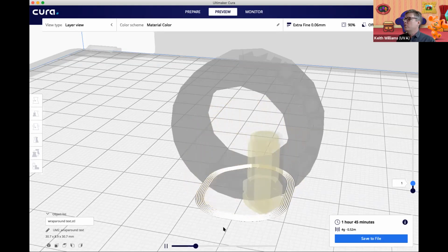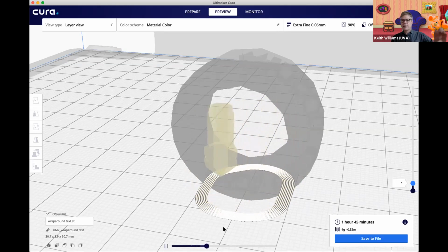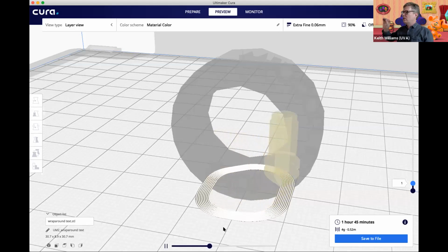So what do you suppose defines the resolution of the print? What limits the resolution of the print? There's actually two different resolutions that we talk about in 3D printing. There is the lateral resolution, which is what you see here. It's all in one plane. What do you suppose limits that resolution? So those of you who have experience icing a cake or putting mustard on a hot dog or something, what limits the resolution? How finely, like if you wanted to write your name with icing or something, what limits that? What's that? The size of the tip.